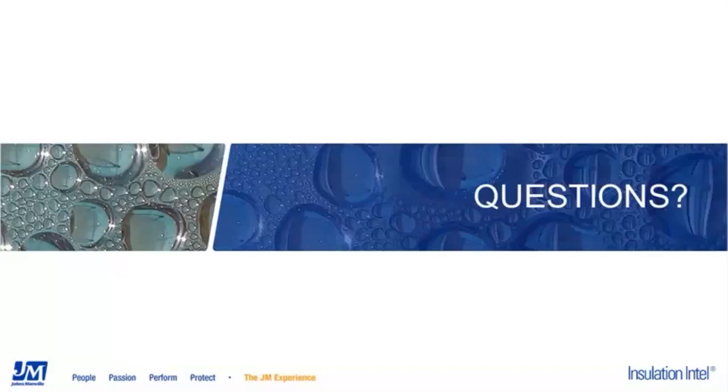Now, since we're talking about chilled water today, I think it's reasonably safe to say that the vast majority of the piping is going to be carbon steel, not stainless. So with that in mind, you can either paint the pipe or you can use one of the corrosion inhibiting gels. There's one called blue goo. That's not the official name, but it's often referred to that in the industry. That's suitable for use on carbon steel pipe. I don't believe they have any evidence that it helps with stress corrosion cracking of stainless steel, but for carbon steel pipes, that can play a role.